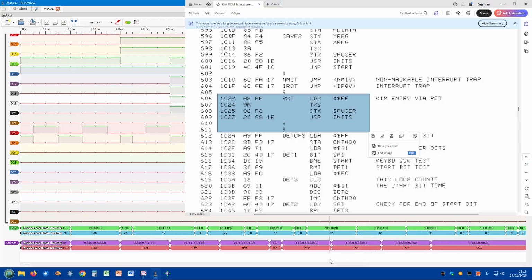So we've got A2 sitting down here. When it starts to execute that instruction, the program counter has been updated and put back out on the address bus. So that's the next location, 1C23. We should have FF in it. Well, where we're reading it back here, we're getting BE. We should have all the bits on. You know, bit 6 is off and bit 0 is off. And when I've done this a few months ago, I can remember bit 0 being off, but not bit 6. So things seem to have got a bit worse.